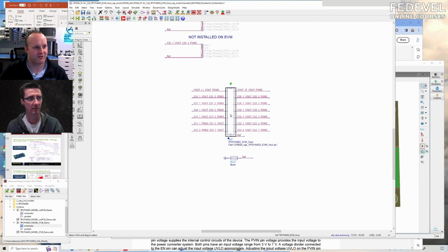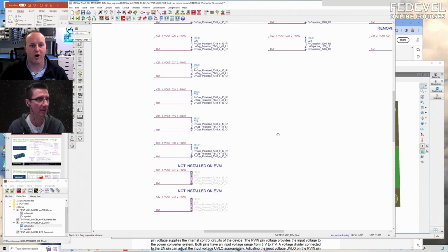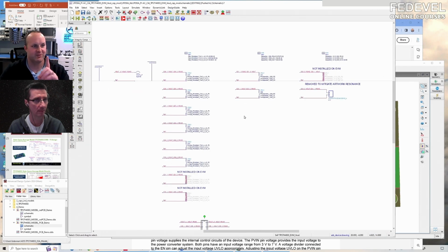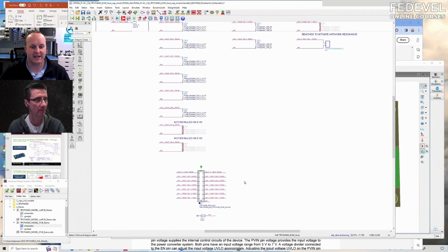This is the V out node of the PCB, and these others are components. These capacitors are all the caps that are installed on that V out. I have a cap hanging at each respective port that was extracted. Remember, there's inductance between that cap and the connection, in that path from where the cap connects to the PDN. How do you model that? That inductance matters. This is where everything matters.